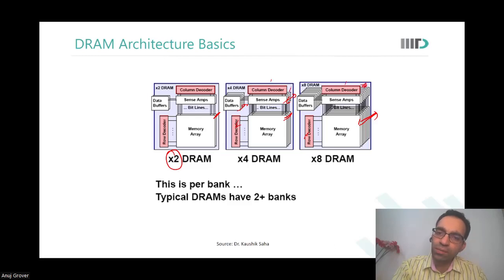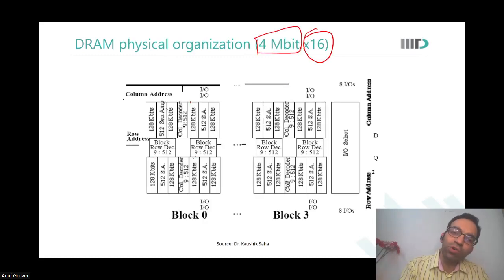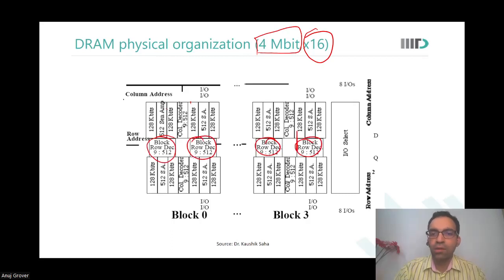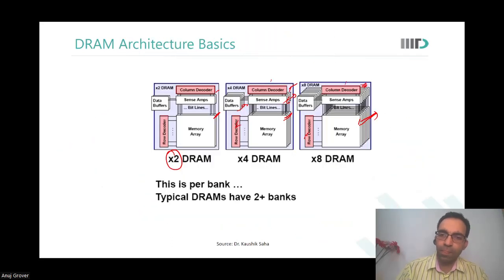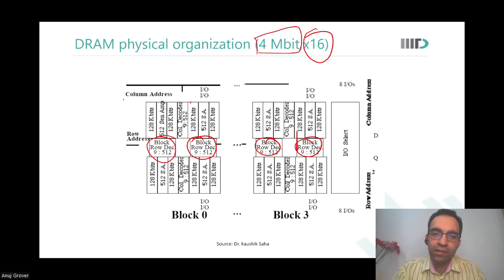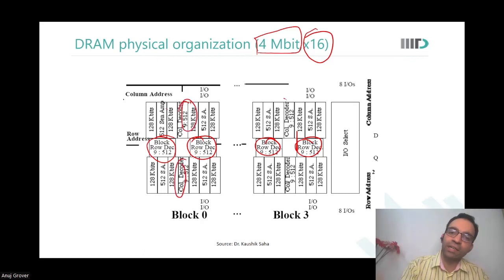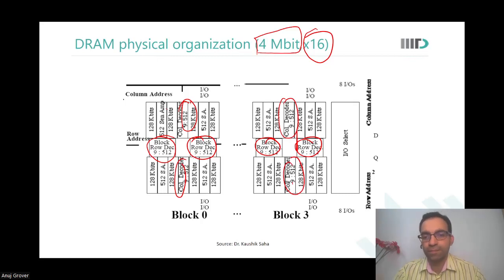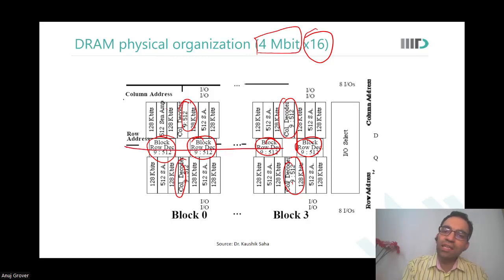I have not repeated them. You notice this? Yes, sir. So the number of bits going down for decode is reduced. However, in a real implementation, you may need to have row decoders again and again. You may want to share them across multiple blocks. So over here, logically, I could share them across all the blocks. But physically, that would mean a lot of capacitance, a lot of RC to handle. So I could have row decoders 4 times instead of 8 times, and column decoders 4 times instead of 8 times, because I could share those column decoders across 2 different pages. Are you able to see this now? All row decoders actually get the same row address. All the column decoders will get the same column address. And therefore, you could share them across multiple banks.